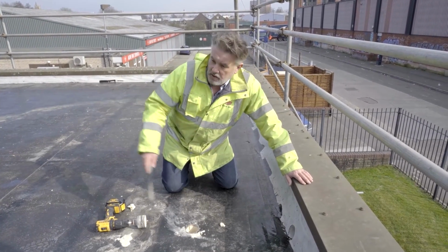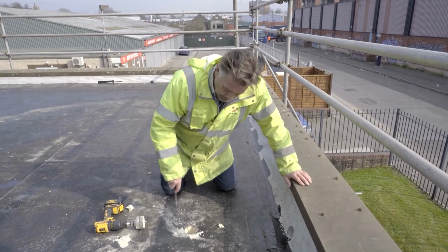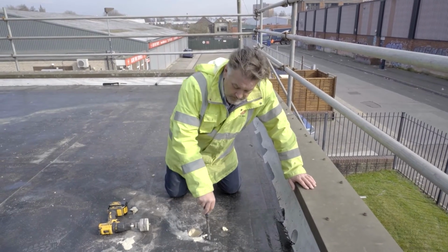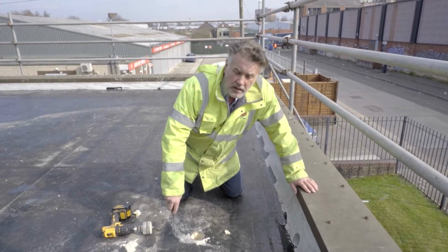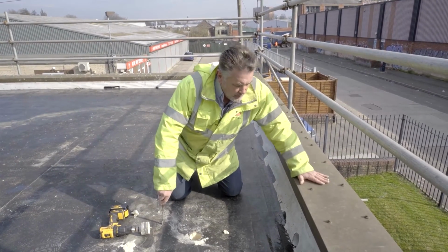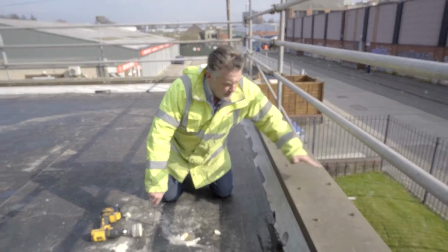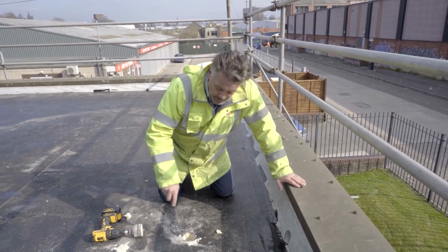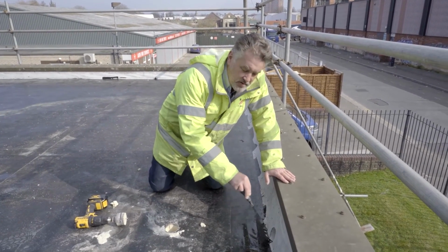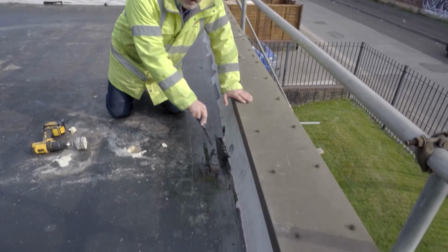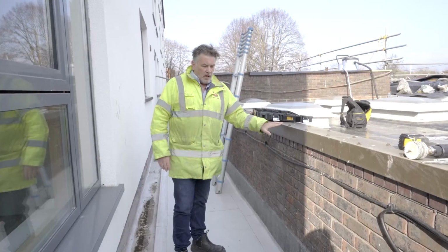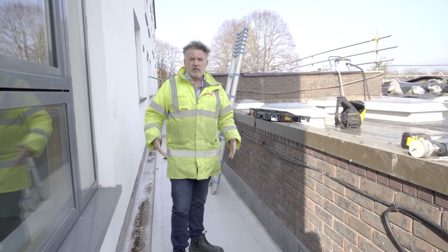I'm going to do a series of cutouts around here just to make sure that this is the case in every location. I'm going to remove this single ply, bond some more insulation on the top, and then put 2 layers of torch-on waterproofing. I'm going to remove these cappings so I can extend the waterproofing to the outside edge. The good thing about the extra 20mm of insulation that I'm going to be putting on here is it allows me to sump the outlets in the existing position, because I'm sure a lot of this ponding water is because of this outlet being high.